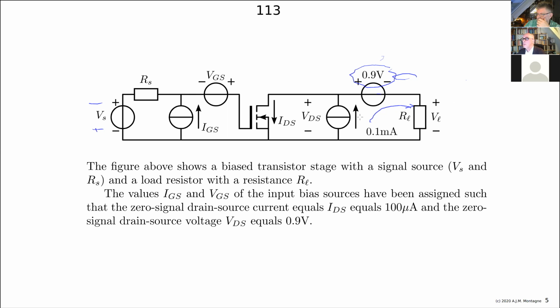And this one has a positive and negative voltage here. The voltage will even increase because the transistor is turning off, and the current is still 0.1 milliamp. So it will deliver more power than before because the product is still negative. The current flows from the minus to the plus. So the product of this voltage and current is positive.